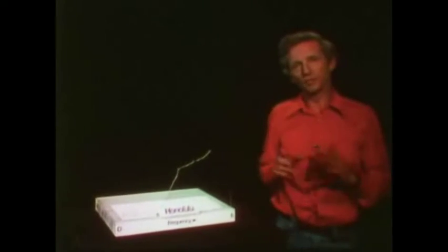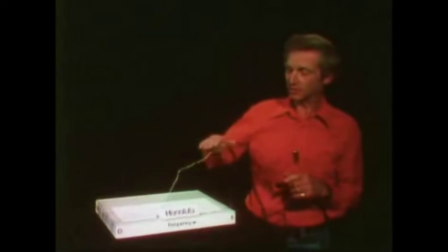Well, first of all, there are always waves in the sea, so that at any one station, Honolulu for instance, the wave recorders would still be registering the general background wave activity, and that would give you an energy density spectrum looking something like this. Its general shape would vary and fluctuate, of course, from hour to hour, but overall it would stay much like this. We say a bit more about the details of that shape in the broadcast notes, but let me just tell you now the frequency from 0 to 6 cycles per minute, and here, of course, energy over frequency.